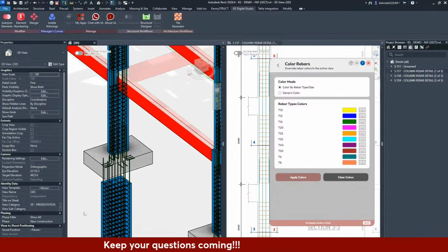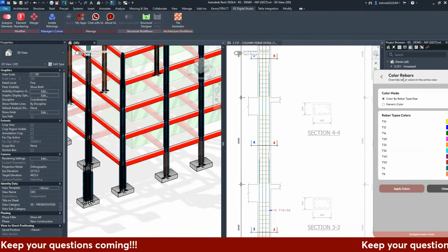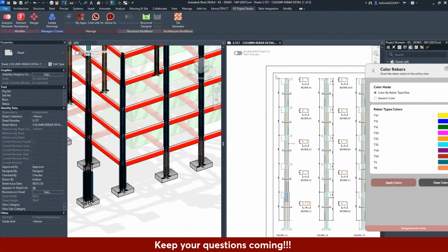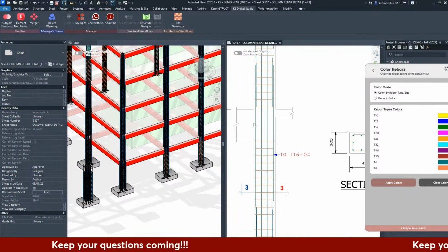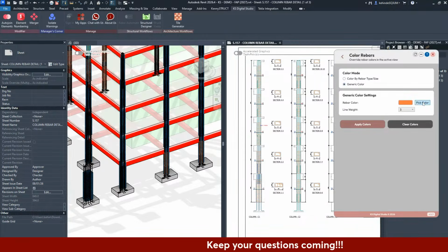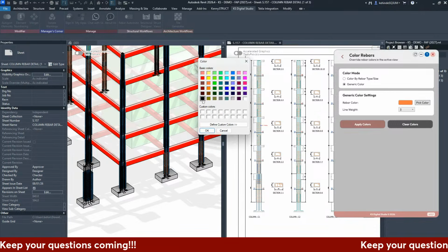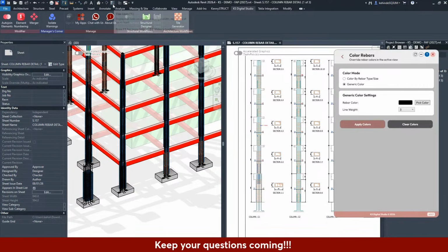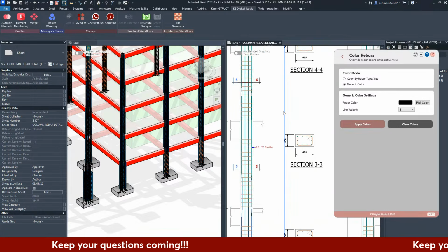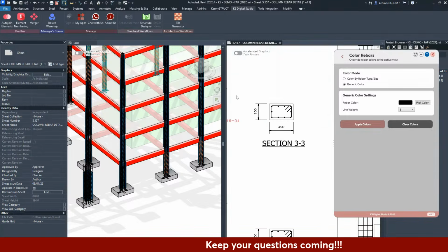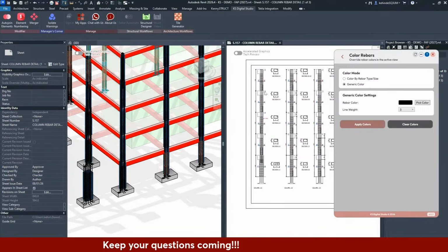Yeah, so for your view, I know most people like to make their colors dark grayscale. So you don't want to have green, yellow, orange on your elevation view. Just come to generic color, activate this view, pick black in this situation, and check my, what's this tool called, thin lines. Make sure it's unchecked so you can see the thickness of the line. I click apply. So it applies everywhere on the view, on the sheet rather.